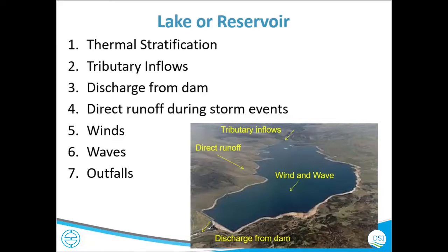So in those cases, it's helpful to find out the drainage areas. Let's say there is a small tributary. You can calculate the drainage area. Then you can go somewhere close to this area where there is a USGS station that will give you the drainage area, where you can pull out the time series of discharge, and then based on that drainage area, you can do a rough approximation of how much flow is coming into the system.